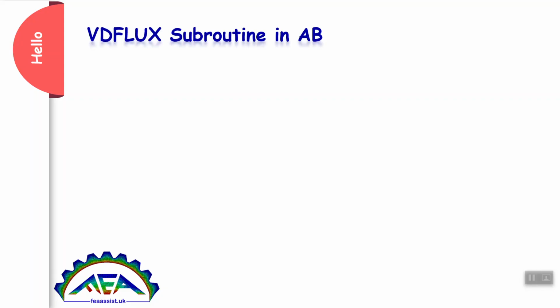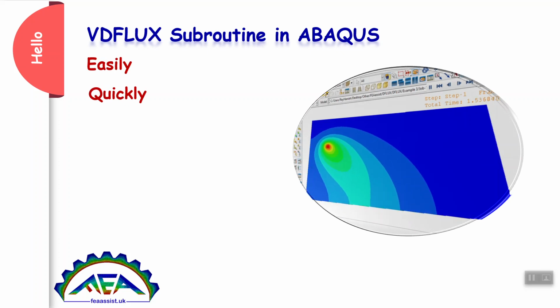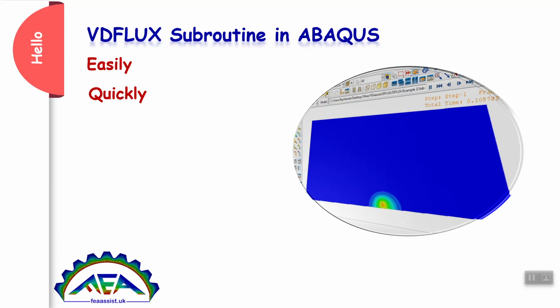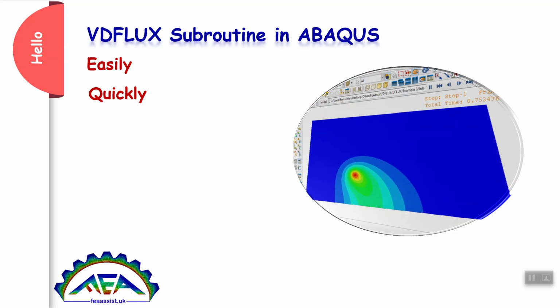Hello, you want to learn VDFLUX subroutine in Abaqus easily and quickly. Actually, VDFLUX is a subroutine to have a movable heat source on your plate or on your sample, which is being used in some processes like welding or additive manufacturing.